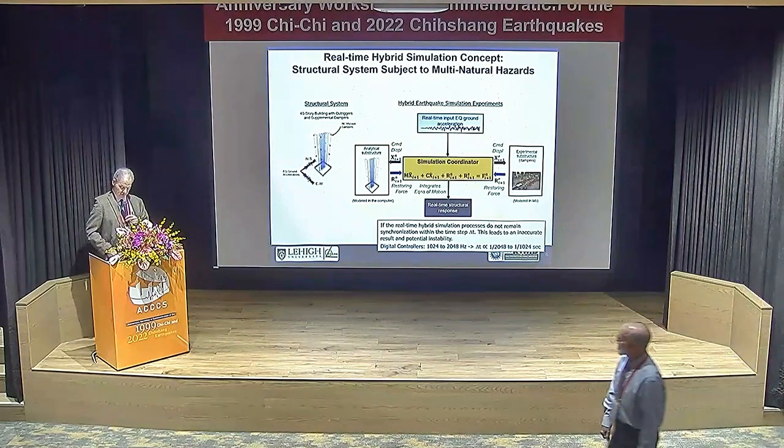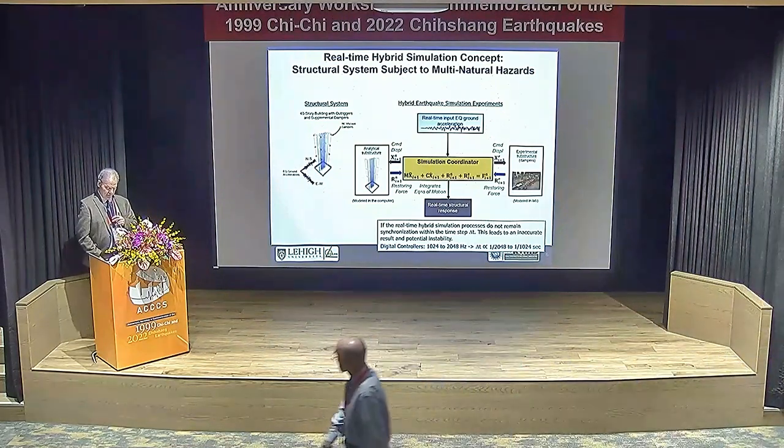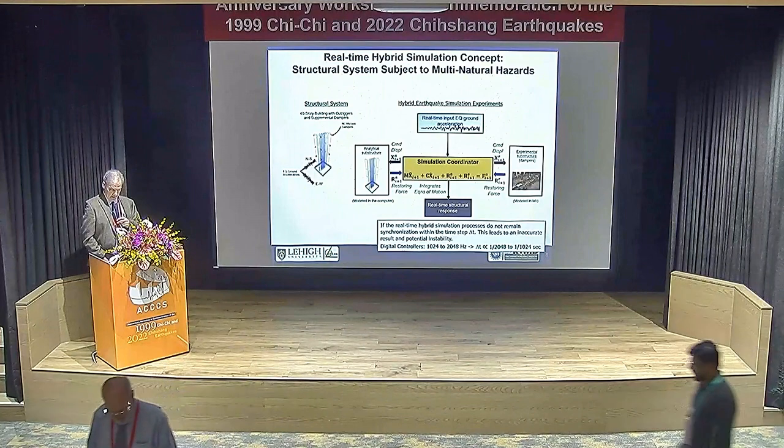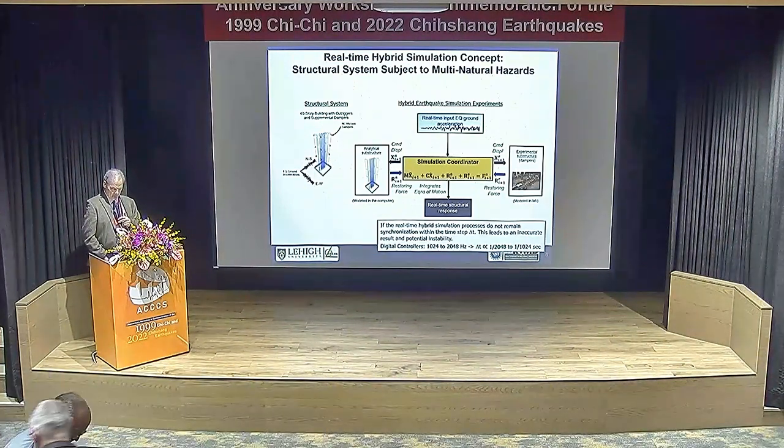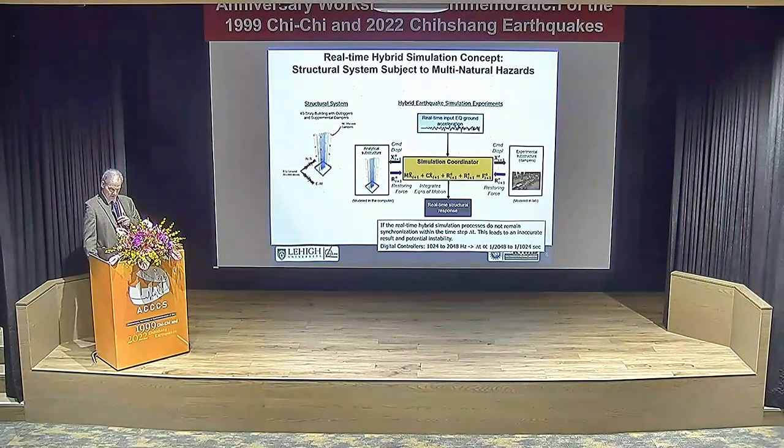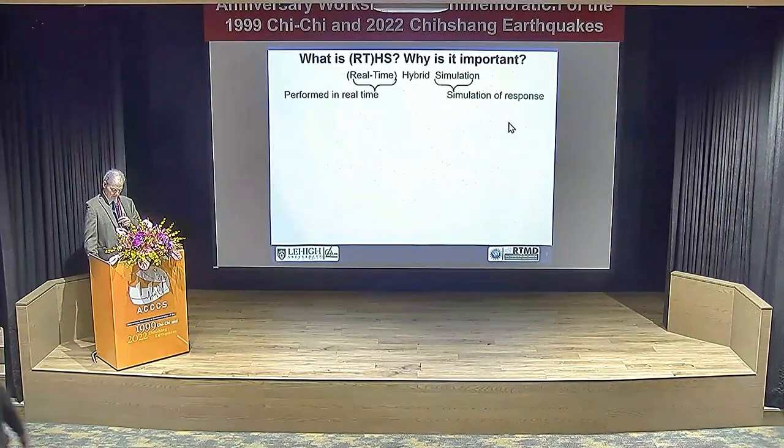Now here's the challenge. This needs to be done in real time. It usually is the multiple of the controller speed, because with a controller, everything has to be synchronized. Controller speeds are conventionally 1024 hertz, but there's some now at 2048. You have to be a multiple of that. And if you can't stay within your allocated time step, you will get chaos here.